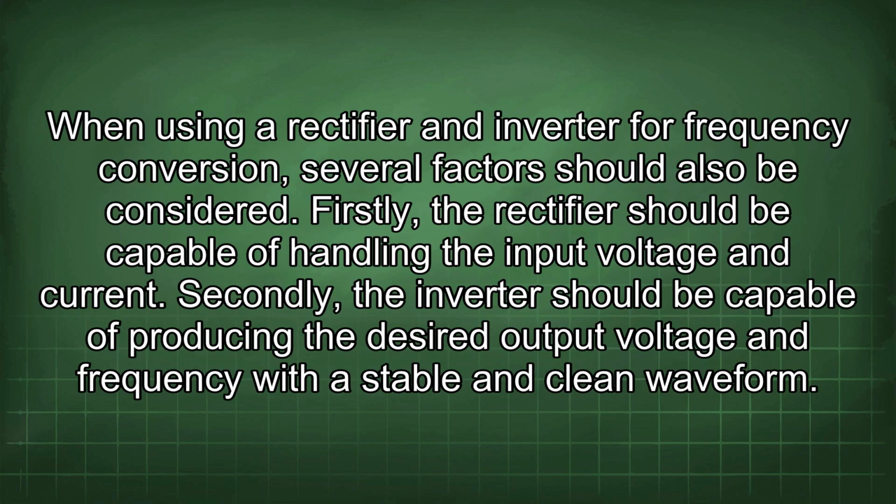When using a rectifier and inverter for frequency conversion, several factors should also be considered. Firstly, the rectifier should be capable of handling the input voltage and current. Secondly, the inverter should be capable of producing the desired output voltage and frequency with a stable and clean waveform.